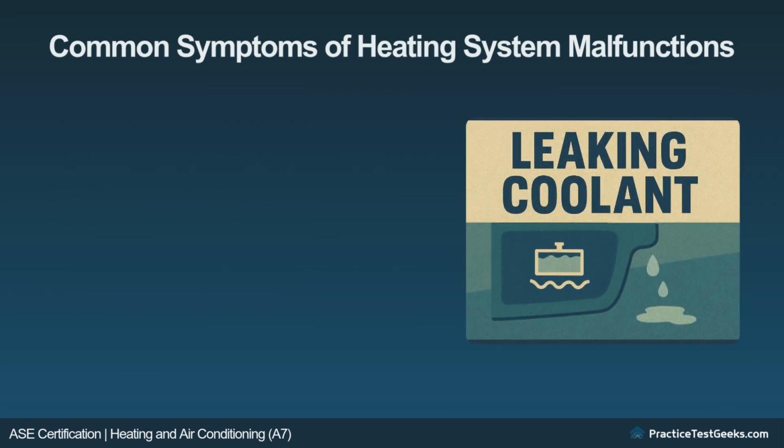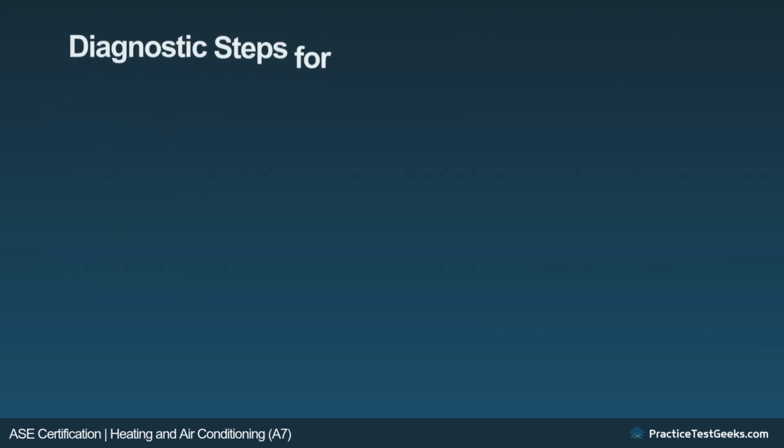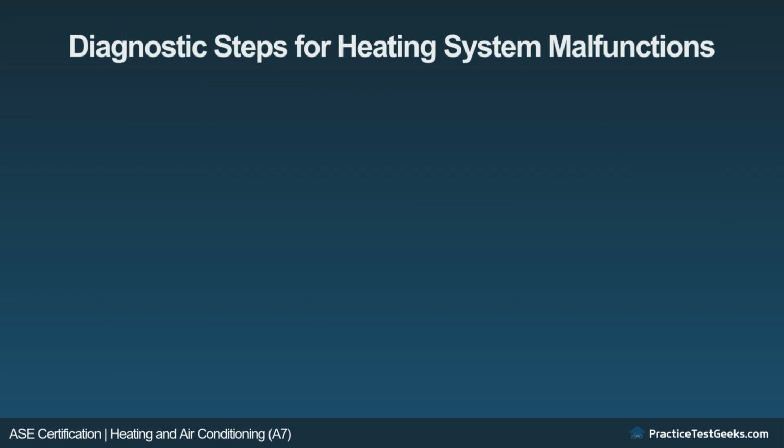Leaking coolant. Symptoms. A puddle of coolant under the dashboard or an unusual sweet smell inside the vehicle. Possible causes. Leaking heater core. A leaking heater core can allow coolant to spill inside the vehicle, often resulting in a sweet smell and coolant puddles.